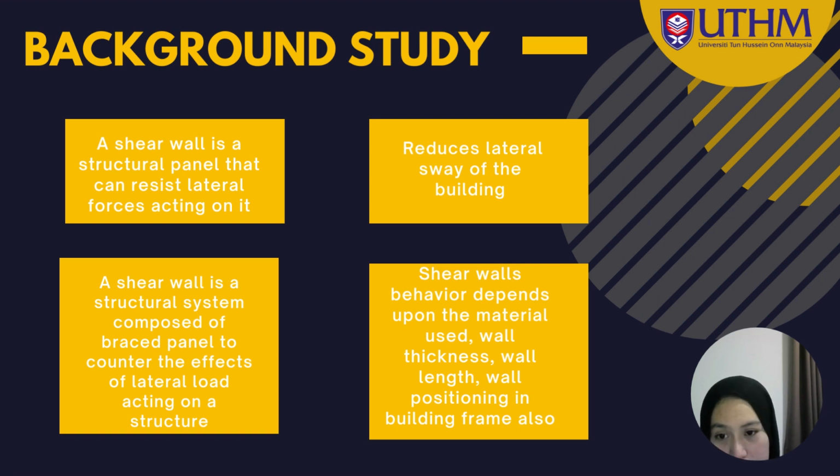In terms of earthquakes, it is said that earthquakes do not kill humans, but structures which are not constructed considering the earthquake force do. Shear walls are built to resist the lateral forces produced during an earthquake or wind. Shear wall behavior depends upon the material used, wall thickness, wall length, and wall positioning in the building frame also.